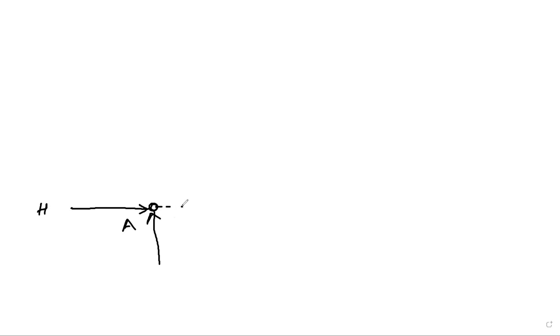This is at A. This is suppose point G. The coordinates of that point, as you know, X and Y with respect to A. So we have to apply the unit load at a distance X from A, and RA and RB are already known to you.